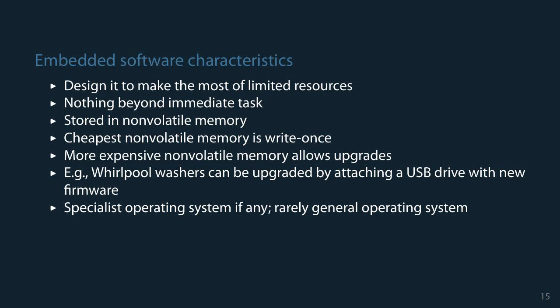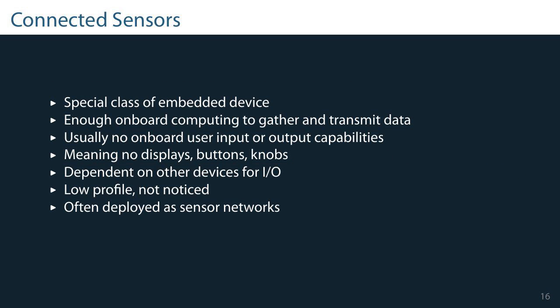And speaking of firmware, there's a specialist operating system, if any. There's rarely a general operating system. Connected sensors constitute a special class of embedded device. They have enough onboard computing power to gather and transmit data, but usually no onboard user input or output capabilities, which means there are no displays, no buttons, no knobs. They're completely dependent on other devices for input-output.